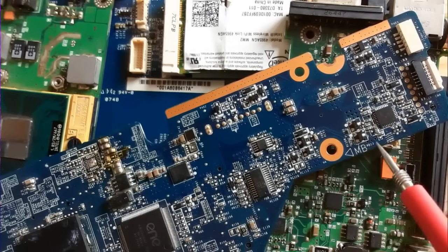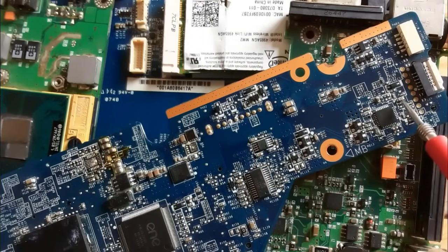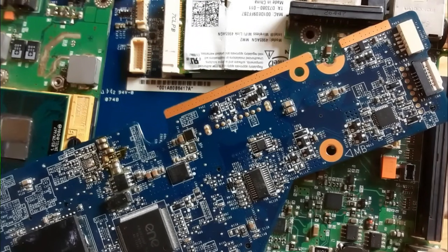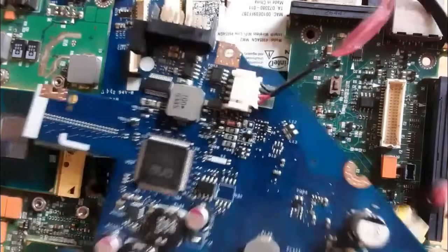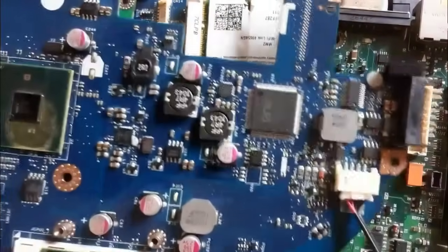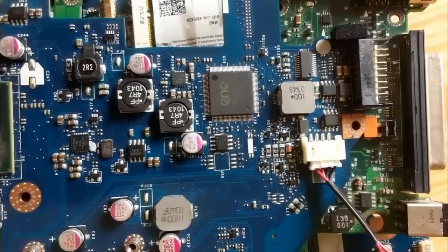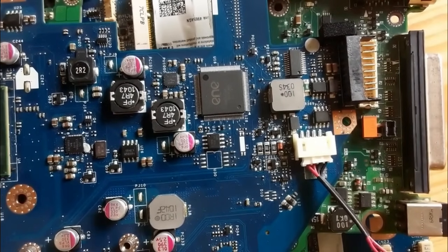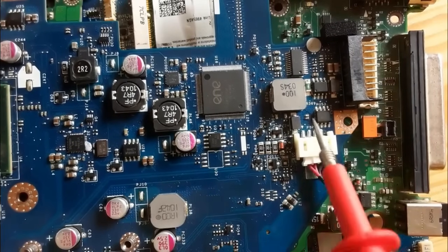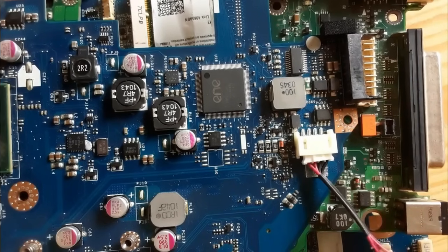Always focus on the capacitors; using the capacitors you can know whether the IC is good or not. Always put the multimeter on the buzzer or continuity option and check the capacitors around the IC. If you find any shorted capacitor, it means the IC is bad. You can also touch the IC with your finger. If you feel heat over the IC, it means the IC is bad.